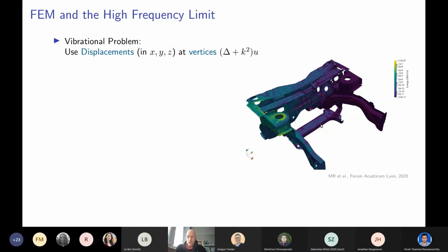And what would you do in order to do things like that? Well, normally the first step is to think of how to describe your problem. And all these methods, these FEM methods, are based on the fact that you use a discretized mesh of whatever it is you want to describe. So if we would zoom in here, we would see hundreds and thousands and tens of thousands of triangles and quadrilaterals, discretizing this complicated structure in locally flat small patches. And then your aim is to solve some partial differential equations. So for example, here, the Helmholtz equation on this whole complex and complicated domain.